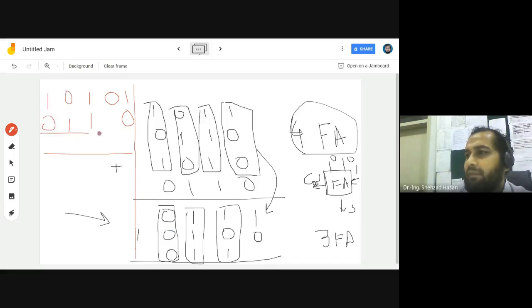So now you can just simply add these numbers. I have introduced a 0 over here because there is nothing coming from this. So now you can use a 5-bit ripple carry adder or any other adder to get your result. So you can see carry save adder is not a proper adder. It's just a reduction kind of thing. So it tries to reduce it using full adders.